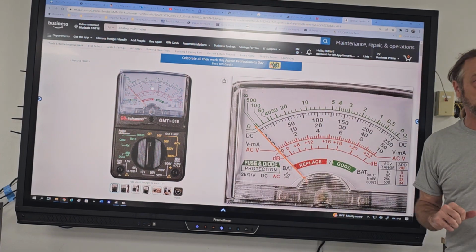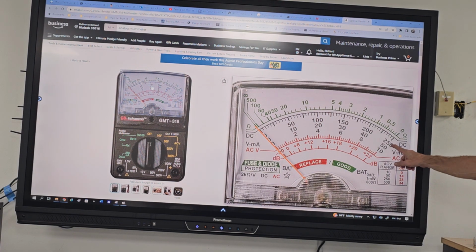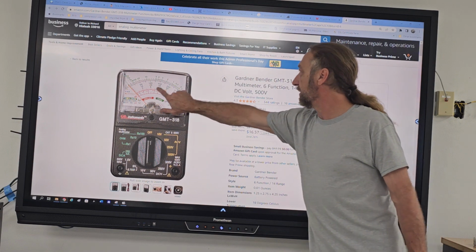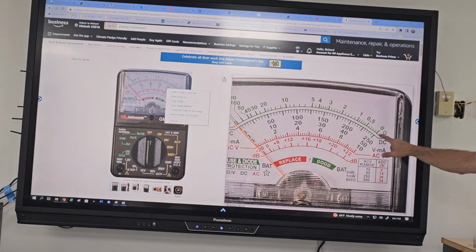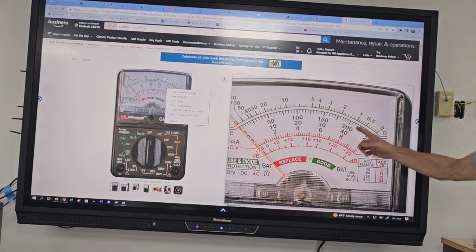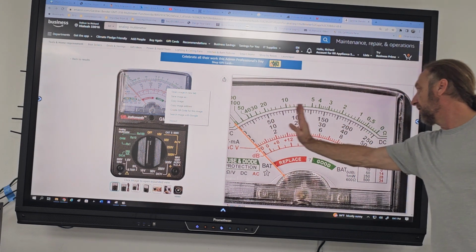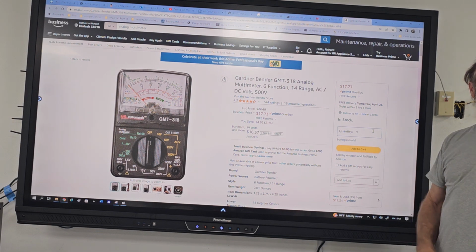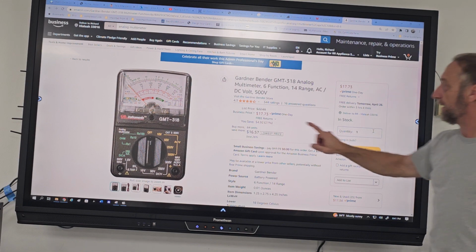I'm not gonna get too deep on that, but if I put it on there and my line is drawn right across there, that'd be 250 volts, 50 or 10, depending on the scale of the meter. If I'm doing voltage, 0 is here, and the highest reading is here. That's as high as that scale read, 250 volts. If I had 260, the needle will peg. What happened, I lost it?